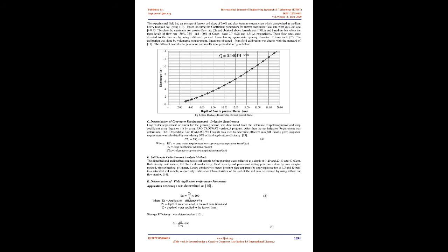The furrow lengths were 25 m, 35 m, and 50 m. The flow rates were 50%, 75%, and 100% of the maximum non-erosive flow rate. The experimental field was arranged as a 3x3 factorial experiment in a randomized complete block design with 3 replications. Each replication had 9 treatments or plots, and each plot had 4 furrows with 2.4 m width.